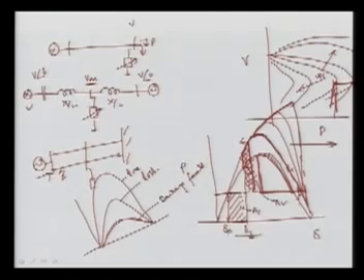Then this line is tripped. The impedance of this line is more than the previous one, and then we are having this line. Now let us suppose we are operating here. What happens during this? The system came here. It was going up to this period, and again this was during the transmission line is tripped and the machine is oscillating here. So you can see this area here should be equal to the area here, and we are having this margin.